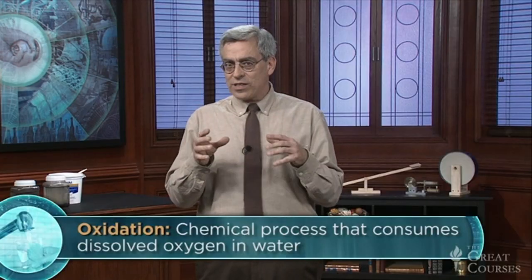Most water also contains some organic compounds, like those dead algae we encountered in our lecture on water purification. Aquatic bacteria and other microorganisms consume these organic compounds as food. This decomposition of organic compounds involves oxidation, a chemical process that consumes dissolved oxygen in the water. And within a body of water, the population of these microorganisms tends to increase in proportion to the availability of food. Well, as we've seen, wastewater is loaded with organic material, primarily from human waste, even after primary treatment.